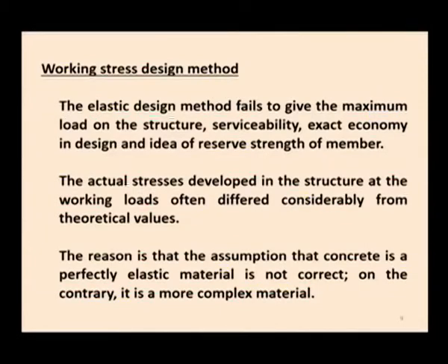Then they found the ultimate load design method. In the working stress method, they had taken concrete as an elastic material, but here they have considered the inelastic and plastic behavior of concrete and steel. Here the loads are multiplied by the factor of safety to arrive at the ultimate load, and the ultimate stresses developed in the concrete and steel are known real values.